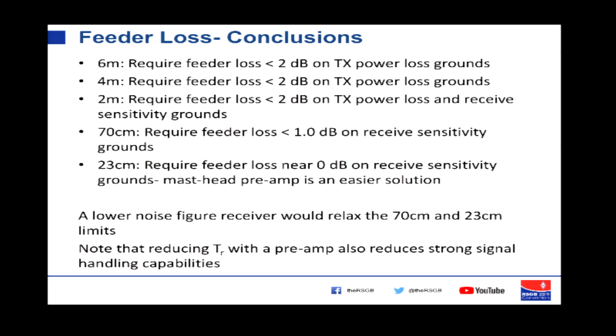And finally, the caveats. If you add a preamp, you will, of course, reduce the strong signal handling capabilities of your system, and that might be, in fact, if you're building contest stations, likely to be a much worse problem than a very small improvement in receive sensitivity.